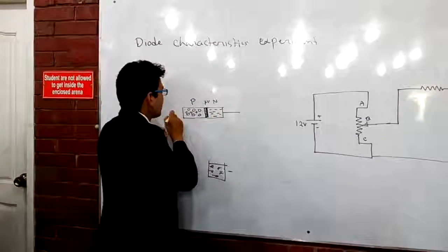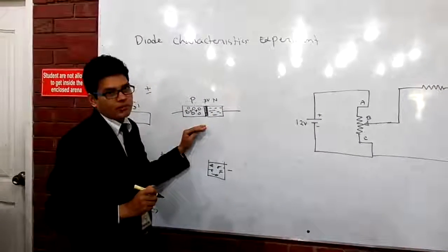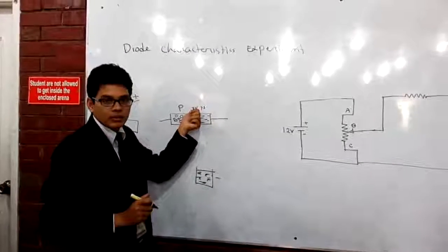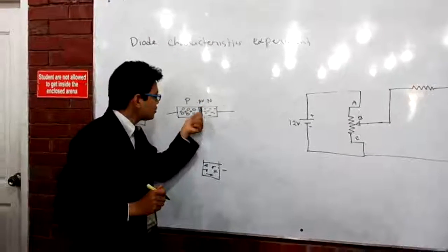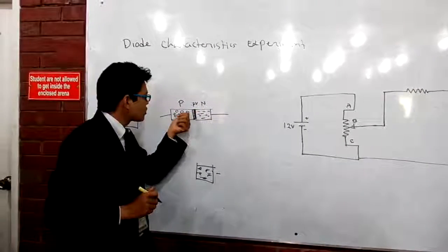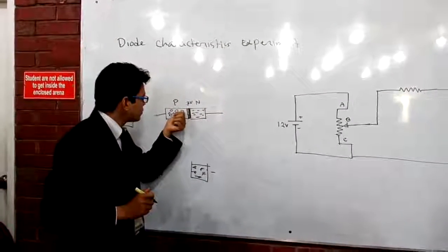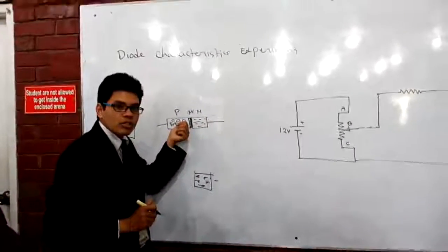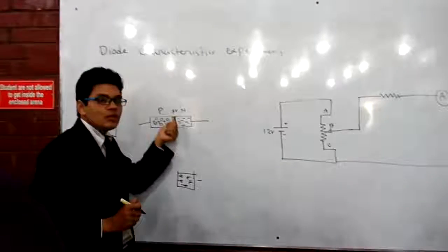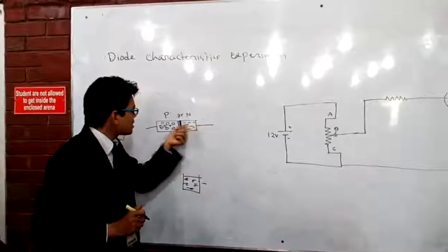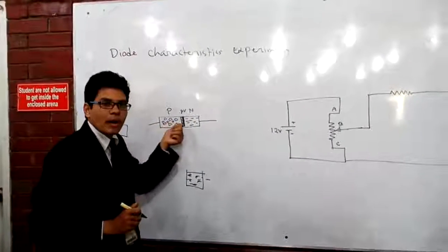It is no longer allowing the electricity to pass through. So this barrier is called the potential barrier, because some of the electrons got mixed up with some of the holes, and they become a neutral area with an electric field, and that opposes the others from combining.